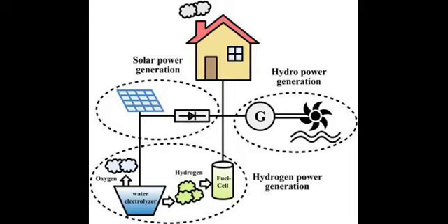Wind energy. Measure wind speeds and directions at the proposed installation site. Historical wind data from local meteorological stations or online databases can be used to estimate the average wind resource. Hydropower. Evaluate the water flow rate and the head (vertical distance) available for hydropower installations. Stream flow data from relevant authorities or hydrological studies can be utilized. Biomass energy. Analyze the availability of biomass feedstocks such as agricultural residues, forestry waste, or organic waste generated by industries or households. Geothermal energy. Conduct geological surveys and exploratory drilling to assess the potential for geothermal resources in the area.